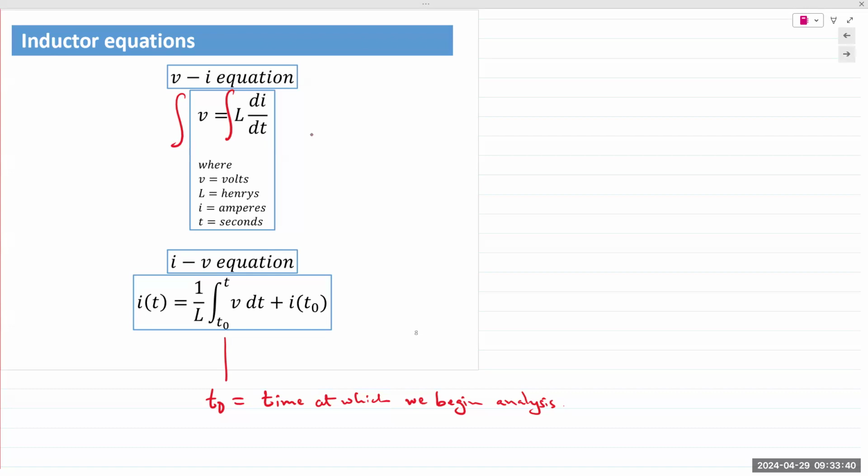So for an inductor, we always talk in terms of the input current, and then we find the voltage when an input current is applied to an inductor. So V is equal to L di over dt. When we get to capacitors, we talk in terms of applied voltage, and we find the resulting current. So I is equal to C dV over dt. Exactly the same structure. Basically di over dt indicates that all the quantities now are time dependent, right? Energy storage devices, energy cannot transfer in an instant. It takes a certain amount of time, and so the quantities are time dependent.